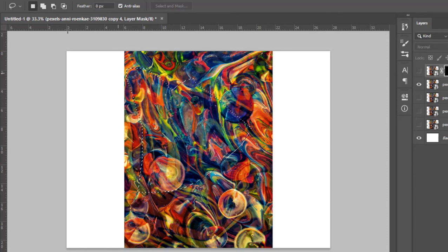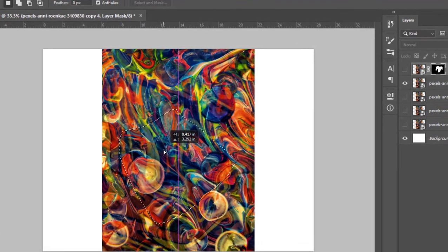Click and select this. I can alternatively use the shift key in order to add a selection. Use alternate key in order to subtract a selection. Use shift alternate in order to multiply a selection. I can make use of this to move this selection to another point I want it to be.